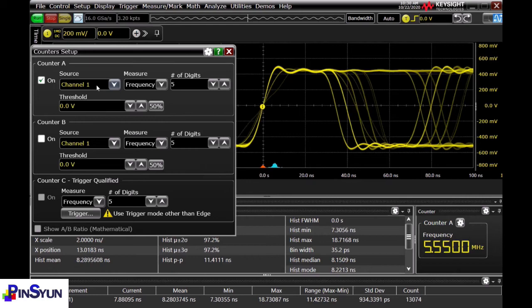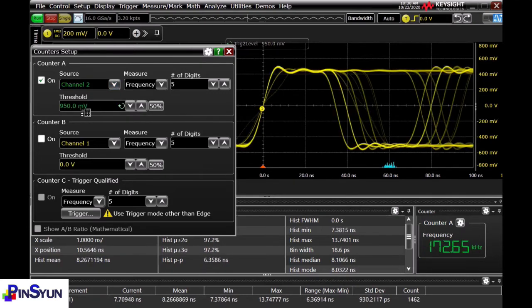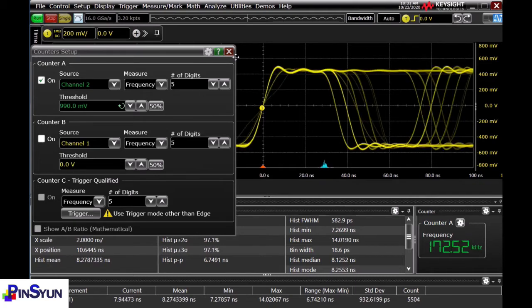But rolling right into demo 3, which is update rate. If you've hooked up channel 2 to the trigger out port of the oscilloscope, you can run through this portion of the demo. Otherwise, it'll still work visually. You don't have to worry about this. This is extra credit. So let's switch the counter to channel 2, set the threshold to kind of like a volt-ish, so they're close enough. And you can see the counter now is measuring the update rate of the oscilloscope in real time because it's connected to trigger out. And so now stopping the oscilloscope breaks that, of course, because when it's stopped, it's not triggering. So you've got to keep the scope running for this one.